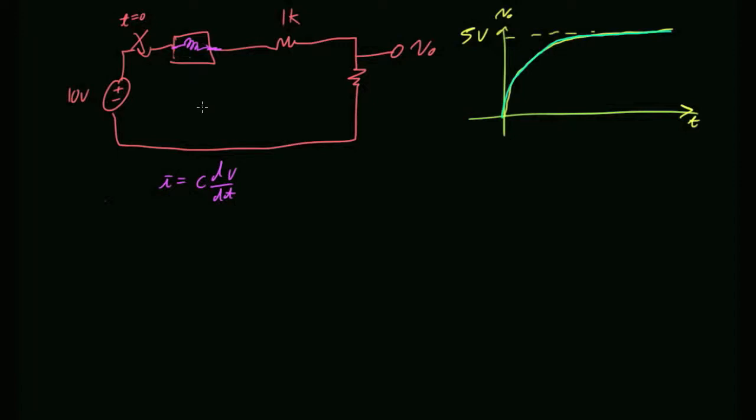Okay? So when you store that, initially the inductor is going to look like an open. But once it charges, it looks like a short. And remember, for the inductor, it's V equals L di/dt. So your inductor is going to charge to some value, and when it does, it's basically going to appear like a short. That's what inductors do, right? When it's charged, it basically just looks like a wire.